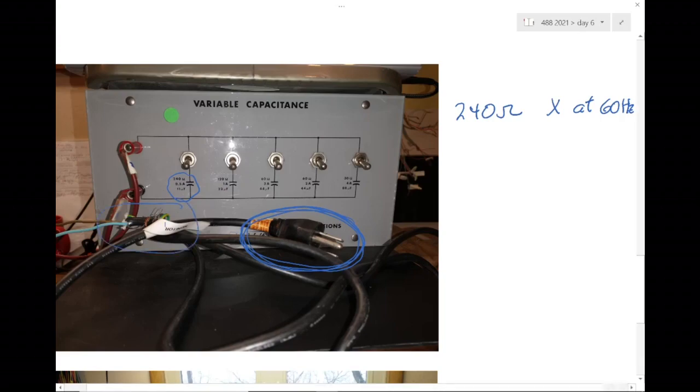But right down here, there's some other specifications, and it's given as 120 volts, 60 hertz. So the X is 240 ohms at 60 hertz. 0.5 amps is the rating. Don't put any more than 0.5 amps, but that's what flows through that capacitor at 120 volts, 60 hertz, and 11 microfarads.